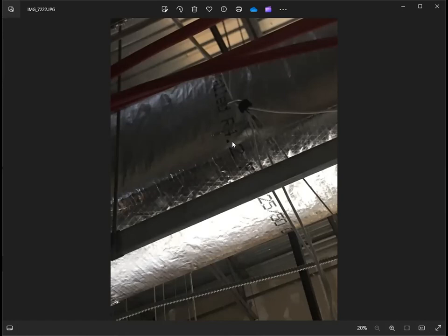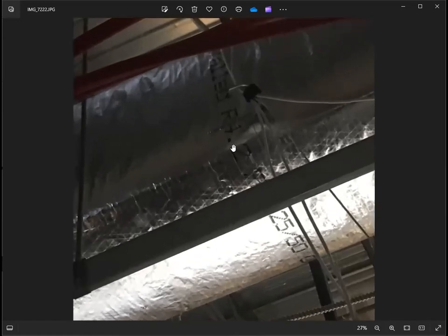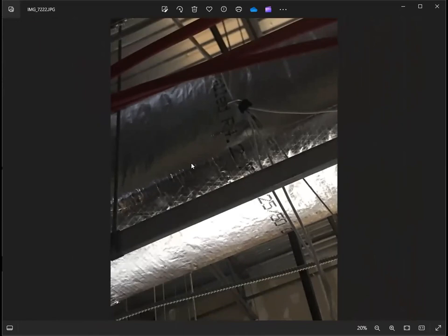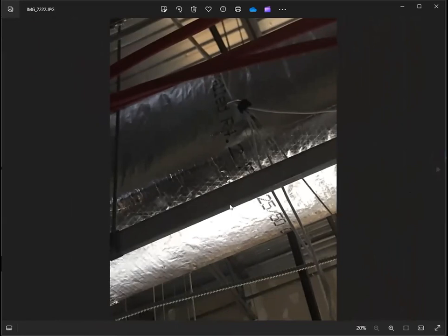So this is a conditioned area. If there is a much different temperature between the ductwork and the atmosphere inside the building, it should be insulated properly, like with an R value of 6. In this case, you only have an R4.2 value. So either the engineer will approve or the contractor needs to correct the insulation of the duct. So take note in the report for that.